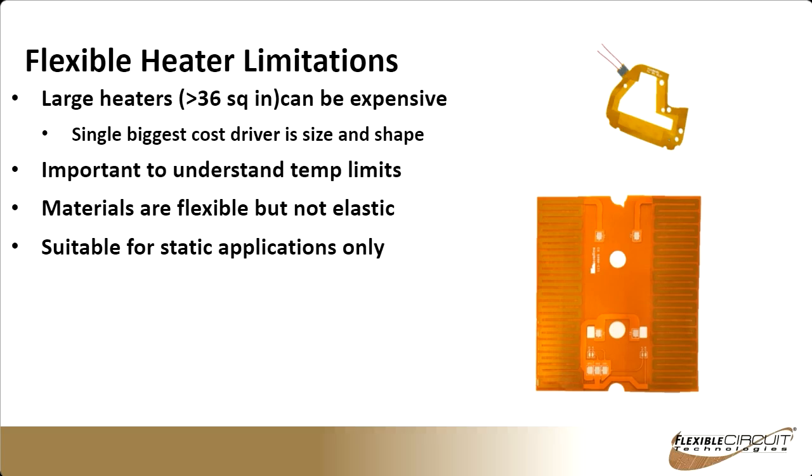So you can wrap them really nicely around a single axis like a cylinder, but they don't fit well around something that's bowl-shaped. To do something like that, we would have to profile the outline of the heater to be more like a star shape, and that would allow us to conform to that. And we can certainly help you if you have a shape that is more than a single axis where you're trying to form the circuit.